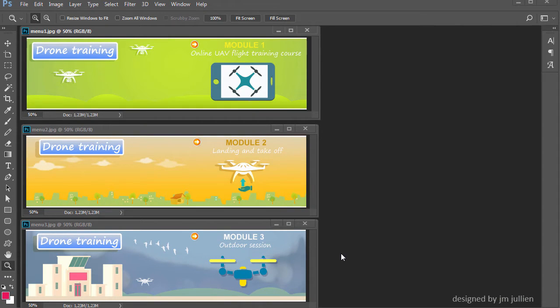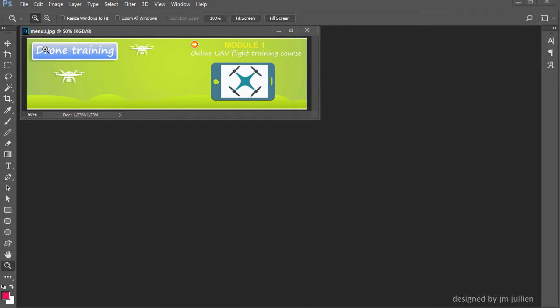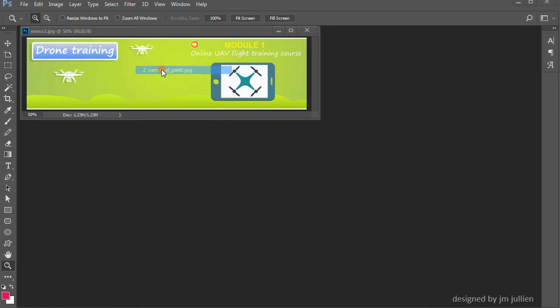the next step is to use these 3 pictures in order to create 3 new files, where we'll put these pictures in pair according to a logical order. The goal is to make the animation of the carousel in Captivate easier. This is why I've created these 3 other pictures that are in pairs.